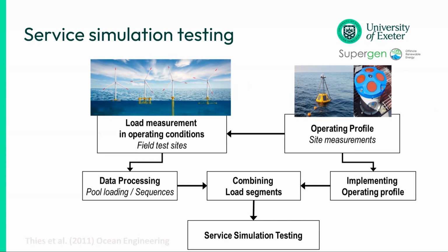But one of the processes is to have what's called a service simulation testing approach, where you think about the operating profiles of any sites you're going to and any load measurements or field installations ideally that you have, but those could be hydrodynamic and numerical models as well, or tank tests. So any type of load measurements and load response will help.